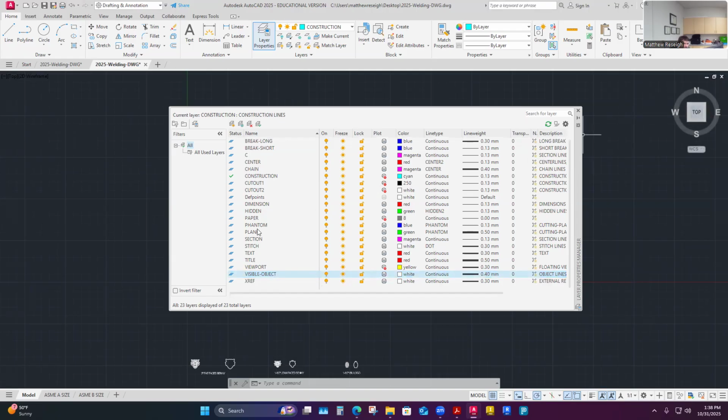The rest are stuff you'd see in your mechanical drawing class or your blueprint reading, right? When we use CAD as drafters, we separate our section lines, our plane lines, our phantom lines, our hidden lines, our center lines. We keep these on specific layers where we designate the line type and the line weight and even a color, just so we can break up the color. Our prints are going to be black and white generally, so the color isn't going to come through on prints. It's mostly for us to keep it organized while I'm drawing, rather than for what my print's going to look like. I draw in color just so I can identify that pretty easily while I'm drawing, and we use that as our advantage because we have that option here.